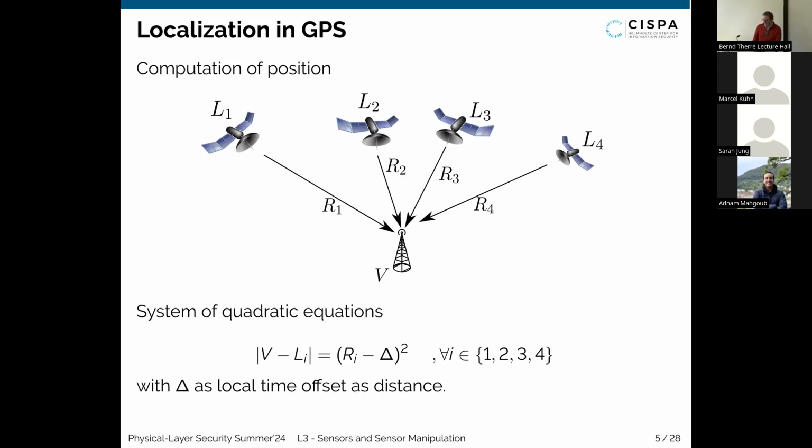But at the very beginning, if we don't know anything, we get a very rough timing just by looking at the timestamps that are in the signals essentially. With this, we have rough location information about the satellite positions because we can roughly compute at this millisecond where they should have been in space. This allows us to get a rough first estimate of the pseudo ranges, and then we can start minimizing errors and over time make this more precise.